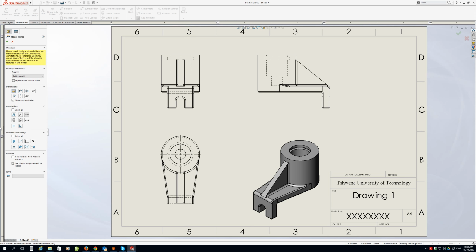The next thing we want to enable over here under dimensions is marked for drawing, also not marked for drawing. Okay, we want to do hole wizard. No, we don't need hole wizard profiles. We need hole wizard locations. Okay, and yeah, so those four. Marked for drawing, not marked for drawing. Instance revolution count, so that's if you use the pattern, it tells you how many. And we want to use the hole wizard locations. Okay, once you've done that, click the tick,